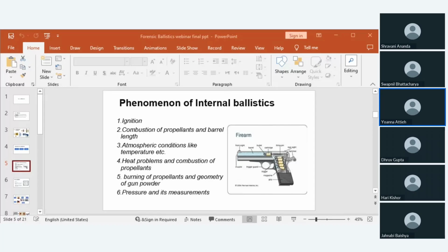Now we have also the chamber size, of course, and the cartridge design, which also affect the combustion and the pressure. So here, guys, the size of the chamber and the cartridge casing also play significant roles in the combustion process. A larger chamber allows more room for the expanding gases, while a smaller chamber increases the pressure more rapidly. Talking about the cartridge casing, it must be strong enough to contain the pressure generated by the combustion of the propellant. A well designed casing will prevent ruptures or failures, ensuring that